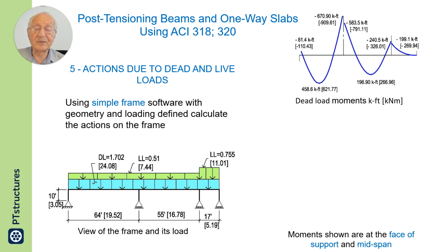I use a simple frame as shown here. Note the end of the bottom supports are on a roller to allow shortening of the member from post-tensioning.